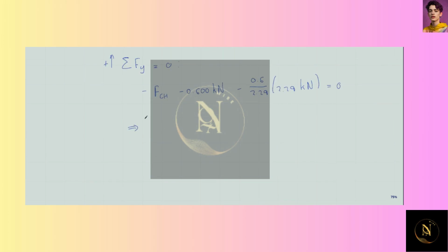So again, we find FCH, and we find this again to be negative. So we get FCH is equal to 1.2 kilonewtons, and this is a compressive force.